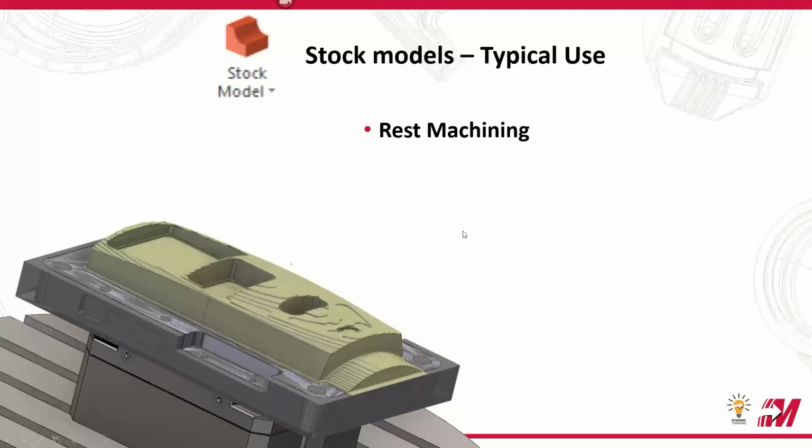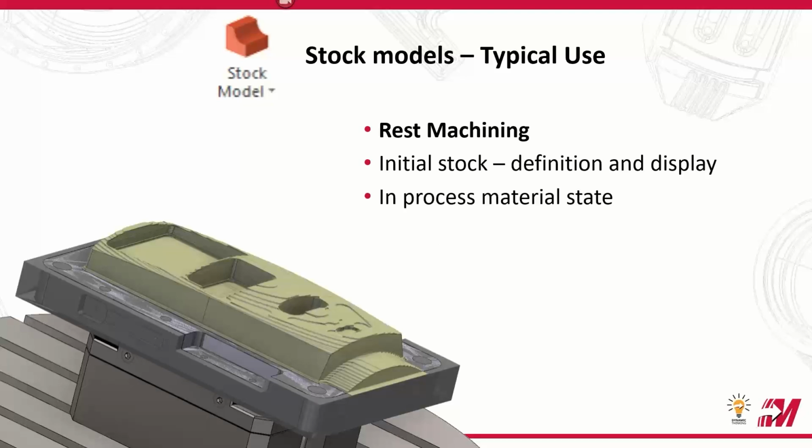Some other things that are very helpful with stock models, kind of a side effect, and we're going to touch on them, are using them for initial stock. I'm going to show you this in a second. And then using them to show the material state in how your process is progressing. You can always see where you have material and where you don't, and it helps you make more intelligent programming decisions.